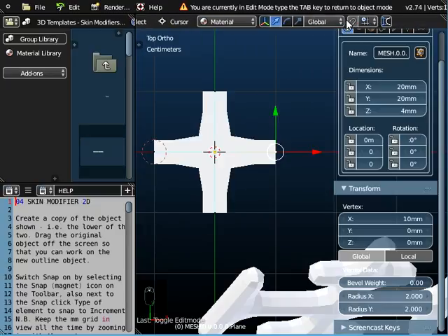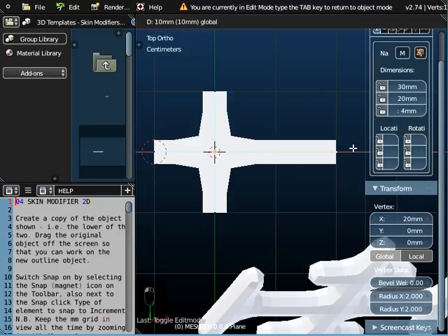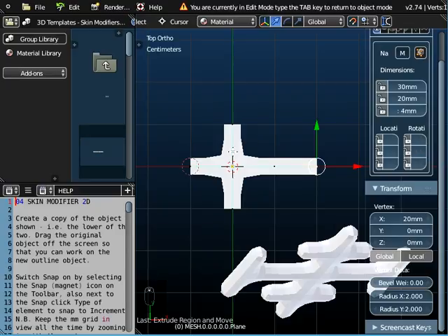We're going to use the snap feature in FluidDesigner. If I switch on the snap feature and switch on increment and move this out here, it will just snap to the next grid. But if I do that, there isn't a control point here where I started. But if I select this control point and press E on the keyboard and extrude it, then what I get is a control point in the original location and a new control point out here. So I'm going to do the same all the way around this object.